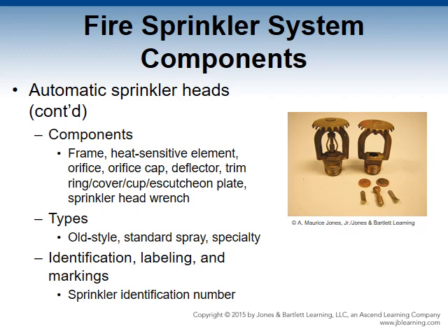We have concealed combustible space sprinkler heads that protect areas such as interstitial spaces with combustible construction material. You have residential sprinkler heads that must operate quicker than your standard fire sprinkler heads. You have concealed heads, flush sprinkler heads, and ornamental sprinkler heads as well.